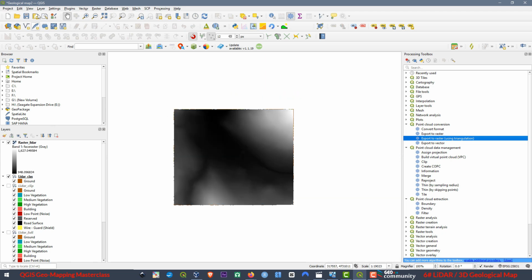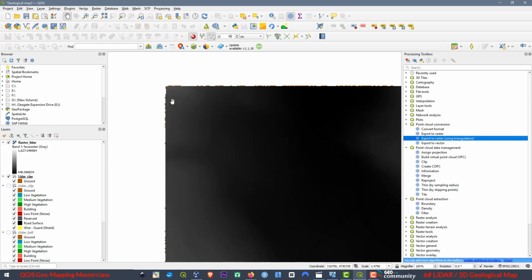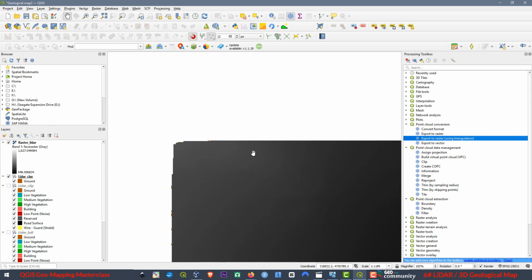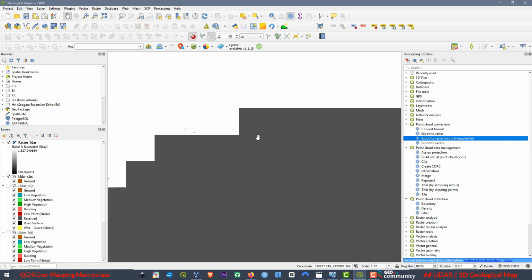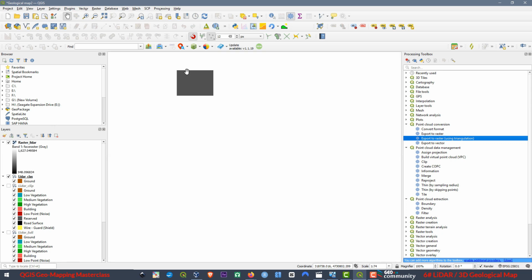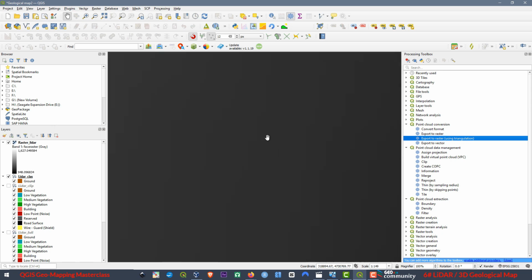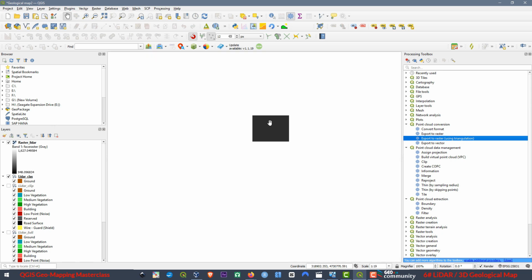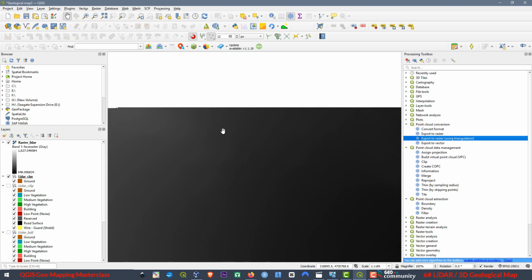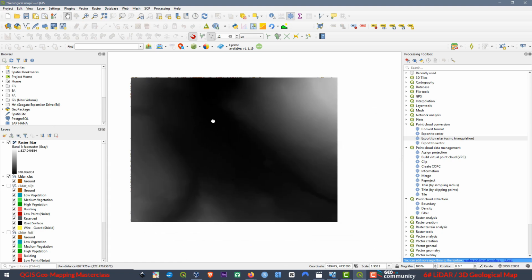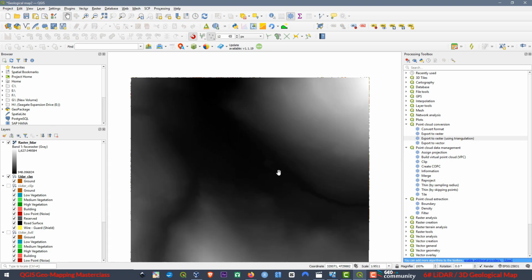And now if we zoom here, I would like to see 1 pixel to see if I can measure the pixels, but it's hard because you cannot see just 1 pixel, right? Okay, it doesn't matter. But you know, the way we interpolated this one, it was just 1 meter each pixel. Now we can also view the digital elevation model in 3D.